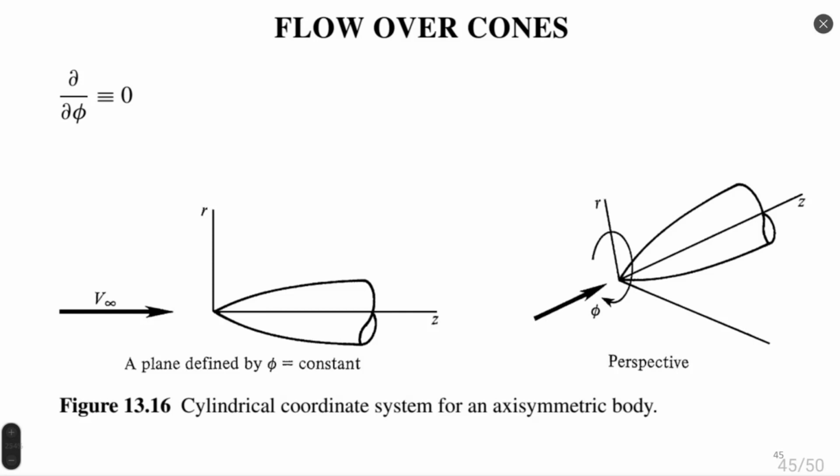Flow over cones is different from flow over wedges, which we already studied before. The difference is that flow over a cone is three-dimensional, and the cross-sectional area of flow changes in a different way than it changes for a two-dimensional body. For example, if I have a two-dimensional body of similar shape, which you can see on figure 16, we would have some object, right?